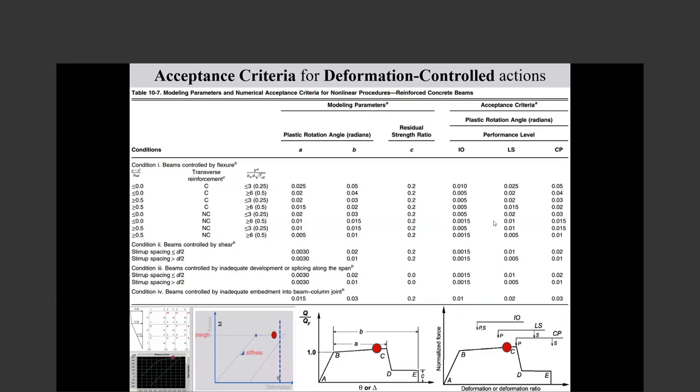So you can see from point A to B and B to C, and then the drop of stiffness. Those effects such as strength deterioration, stiffness deterioration, those cyclic effects are seen in these curves. But any section analyzer usually gives you the response under monotonic loading.